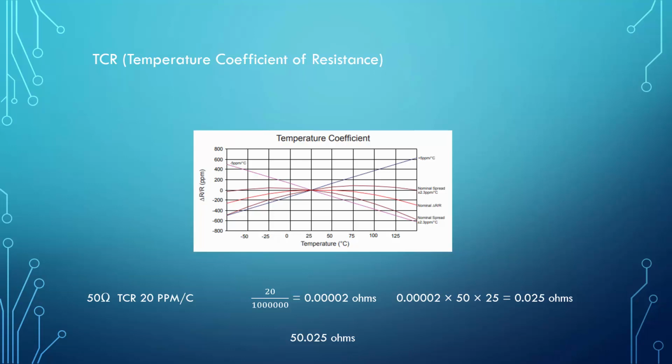For example, if you have a sensor whose output is current, not voltage, and you want to measure the sensor value, you should convert it to voltage to measure this voltage by, for example, a microcontroller ADC unit. To do that, you can pass this current through a resistor. This resistor is called a shunt resistor. Some sensors' output current is just from 0.1 milliamp to 2 milliamp.